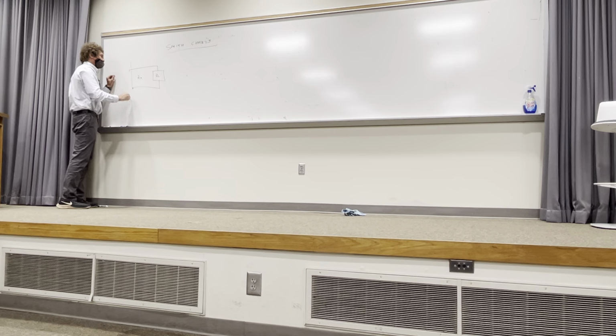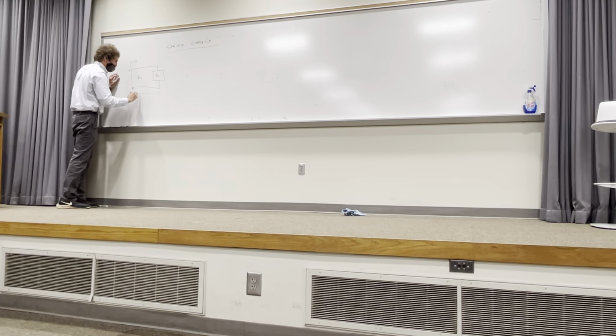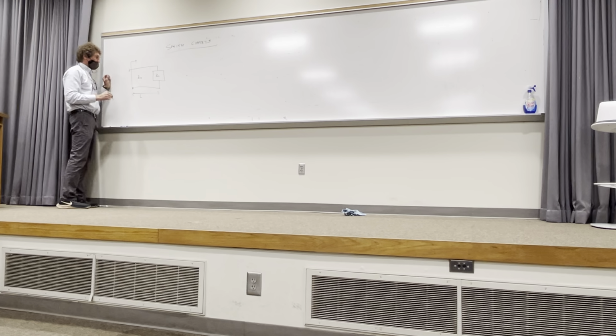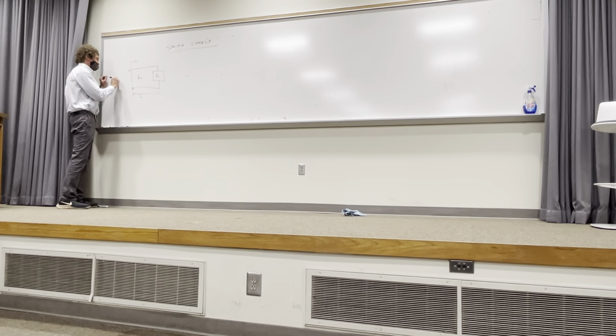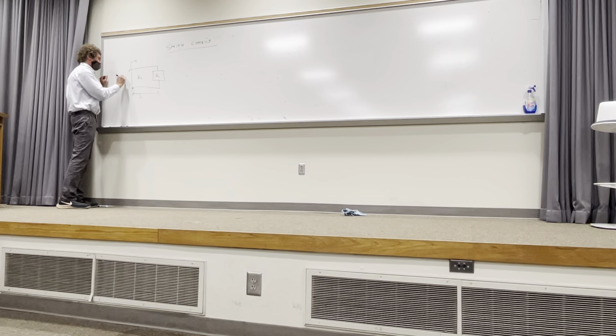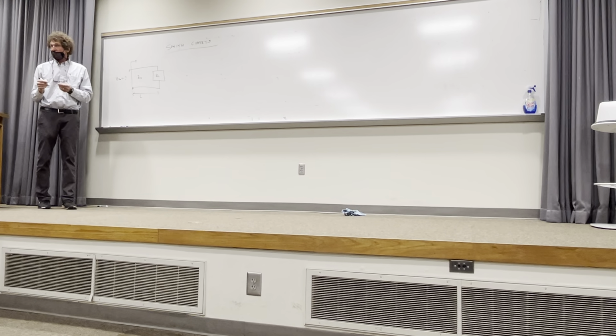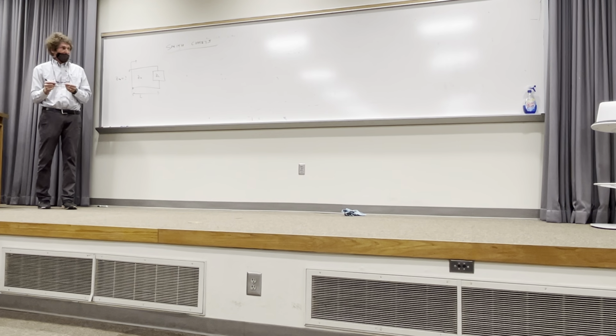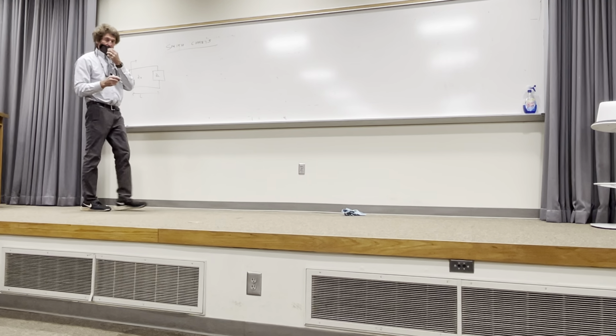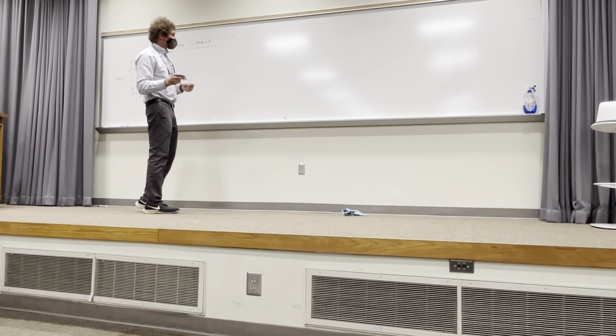I'm going to say if we come down a length L away from the load, and we want to know what Zin is right here, we're going to calculate it using just the Smith chart. You're going to see it relieves some stress because of that other calculation that we just did. It won't be as accurate, but it's accurate enough for anything we care about.